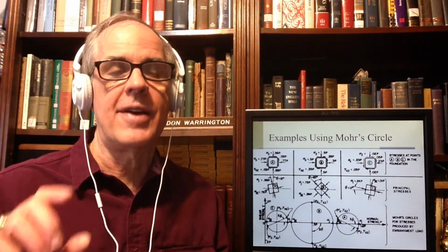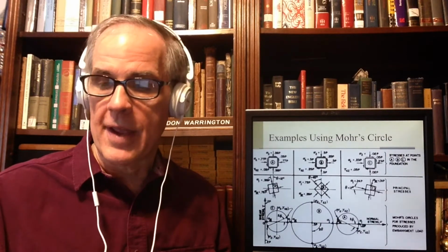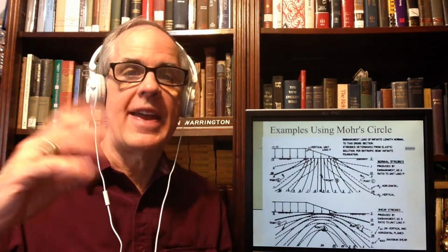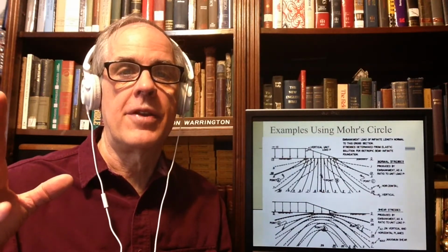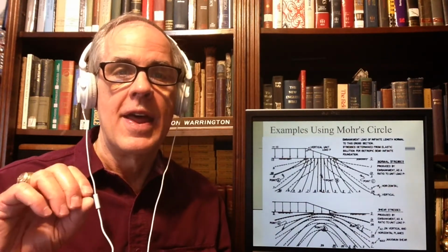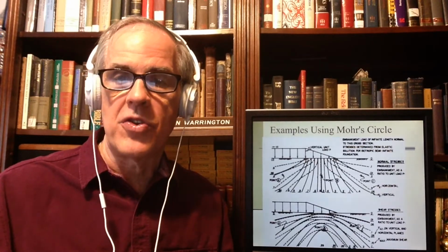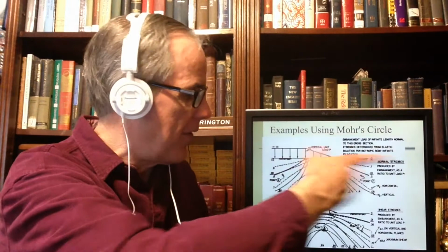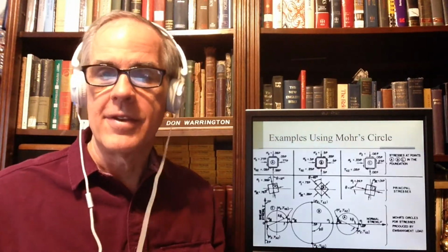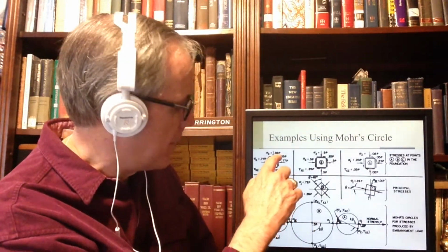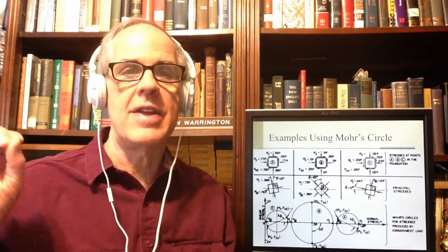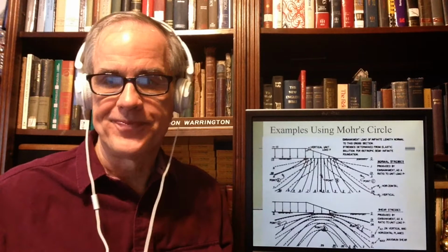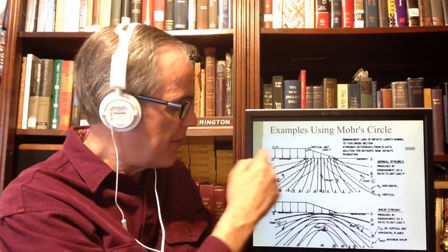I set this up, you remember the example I gave back here where I said, 2 meters, 18 kilonewtons per cubic meter, 36 kPa. That is the uniform surcharge load, and obviously that doesn't apply across the whole thing. But what it is, though, is the baseline P. In other words, the P that's mentioned here is in fact the surcharge in the uniform area.